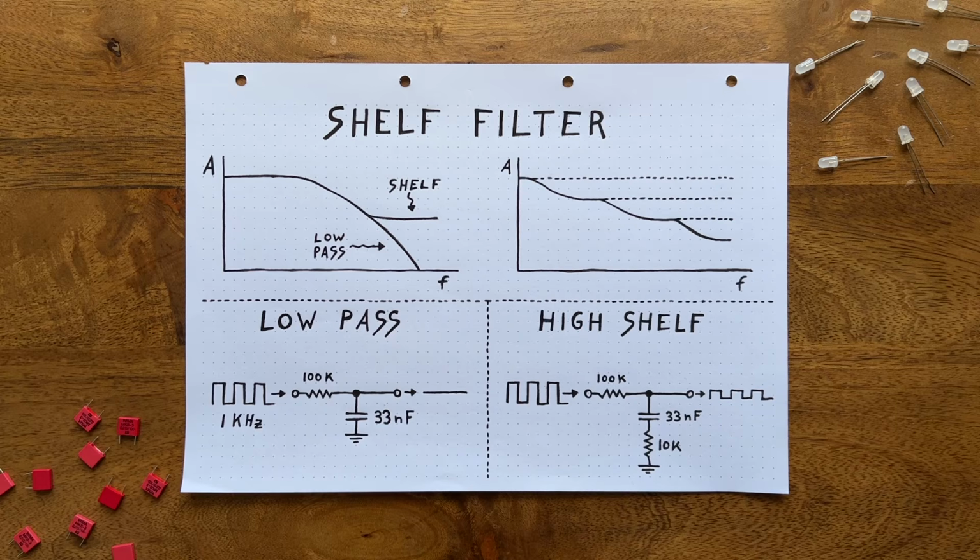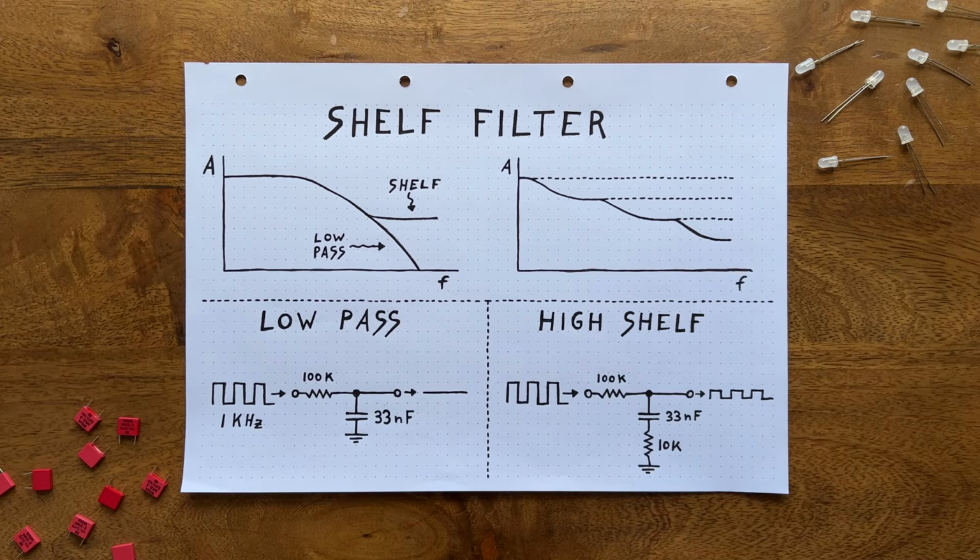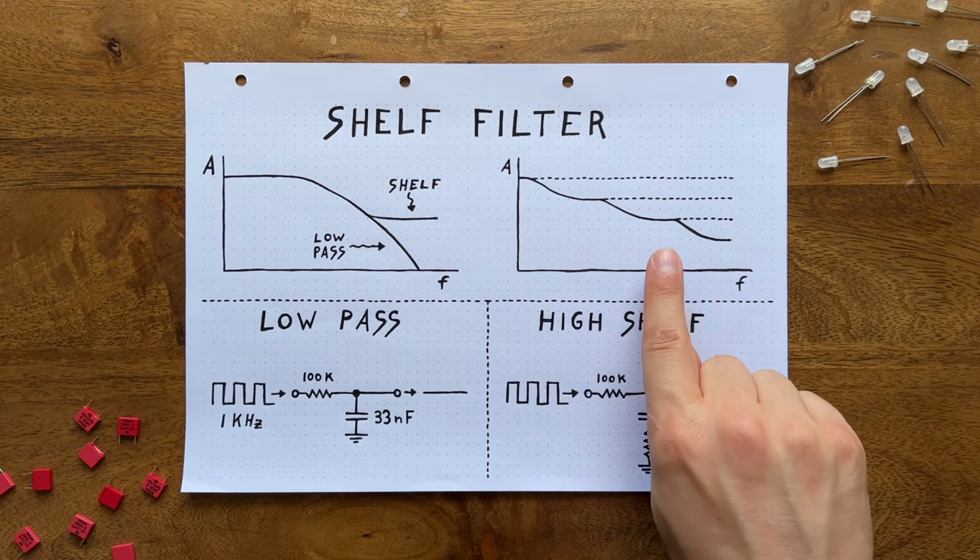Now, how does this help us with our 3 decibels per octave slope problem? As a single shelf filter, it doesn't really. But what if we were able to apply multiple different shelf filter slopes to the same input signal? Because then we could arrange those so that the result approximates a 3 decibels per octave slope. Now, if you really care about precision here, you'd have to use a lot of shelf filter slopes to get something that resembles a smooth line as much as possible. But for me, a rough approximation is good enough, which is why I decided to go with just 3 slopes in total. One for the low end, one for the mids, and one for the high end, giving us this coarsely stepped pseudo 3 decibels per octave slope.